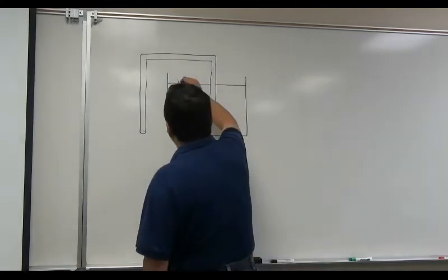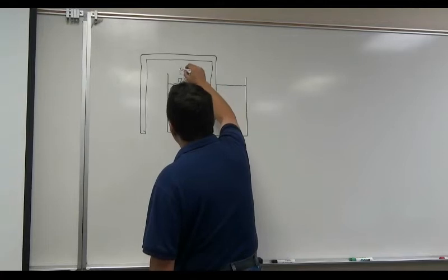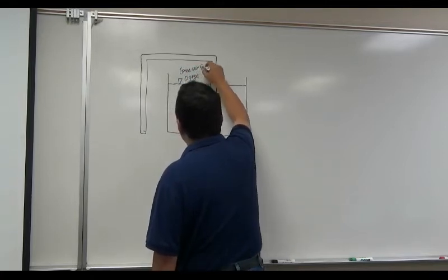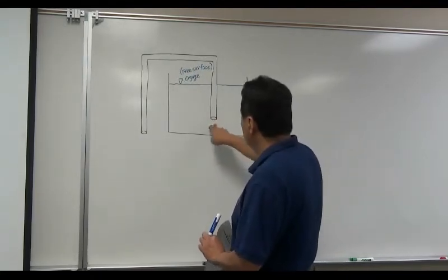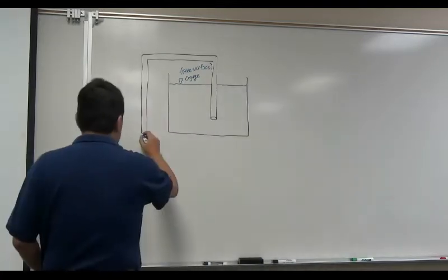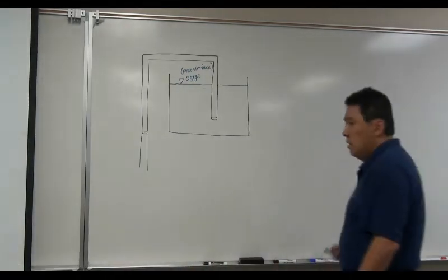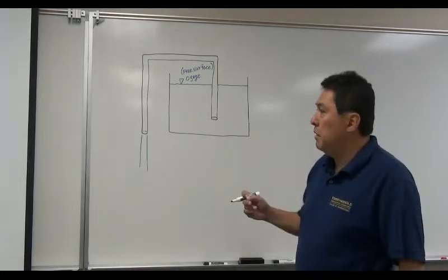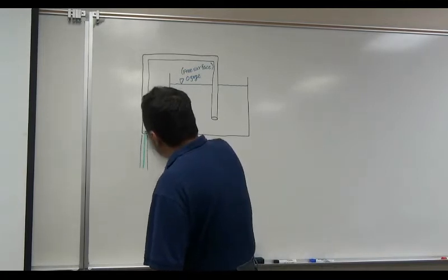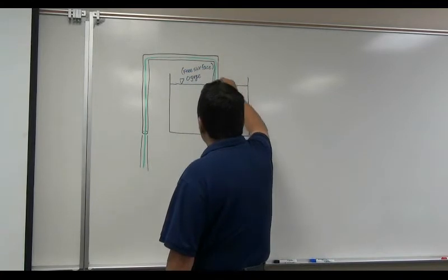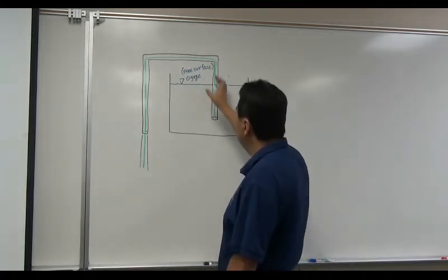Now obviously this is the surface of the water, so we do know the pressure here is 0 gauge. This is a free surface. Okay. So what's going on here is water is sucked right into this side of the tube and coming out this side. I have to first of all draw a streamline because I want to apply Bernoulli's equation to solve this problem. So obviously the streamline is going to be a like flow within the tube, and then the question is, how does the water get into the tube and get out?